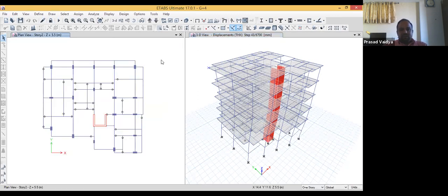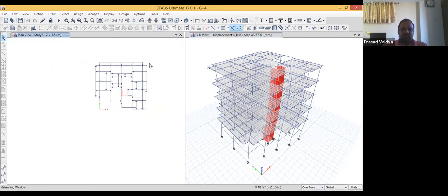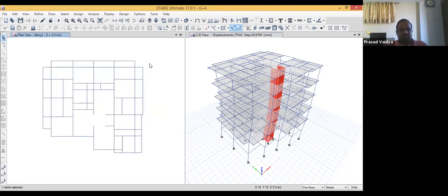You can check this result, but the important thing is that whenever you go for actual analysis, you should always perform a minimum of 3 time histories, and then you can get the output for further processing like design and so on.